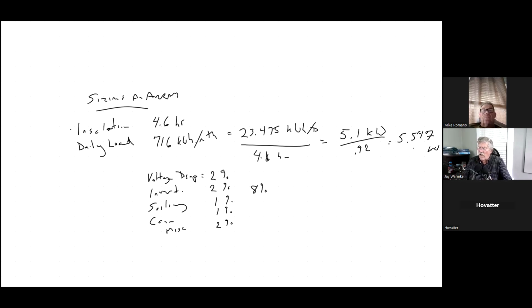If I go to derate and I get a smaller number, I know I did it backwards, because logically, if my system's not 100% efficient, I should not need a smaller array to generate the power I require. I should need a bigger array.